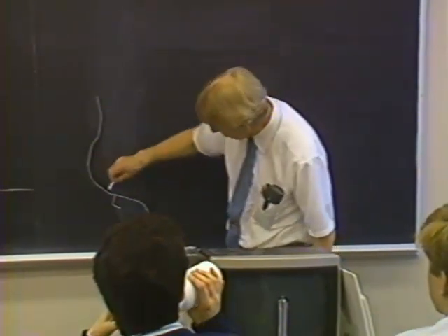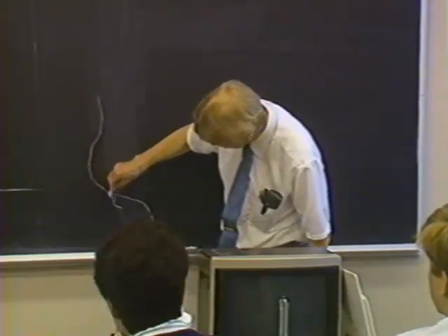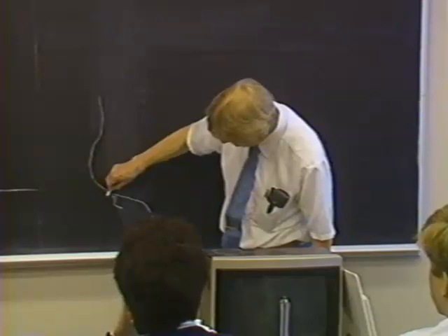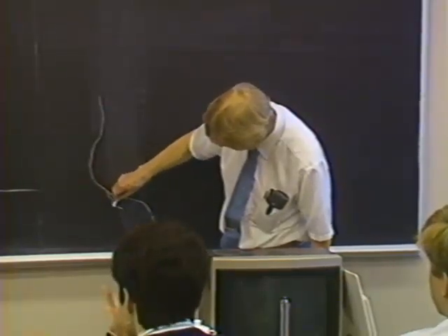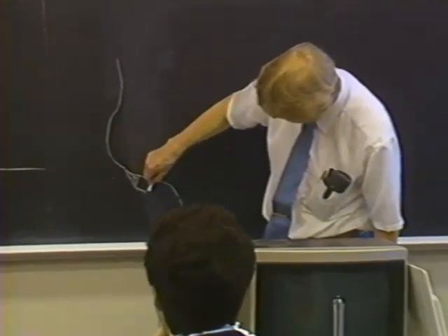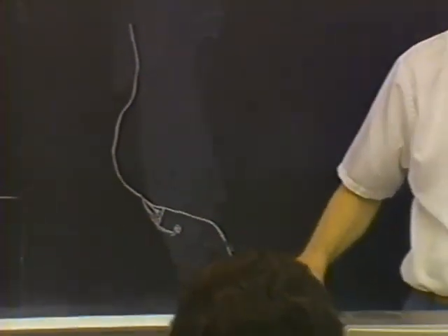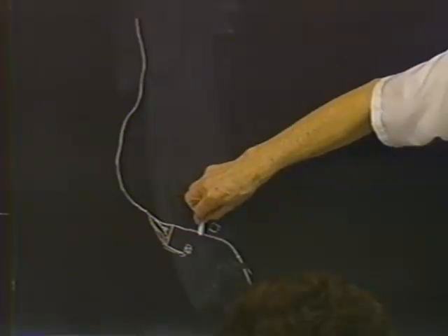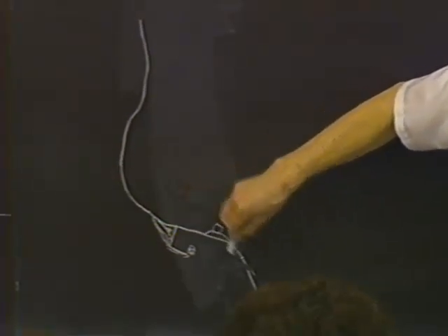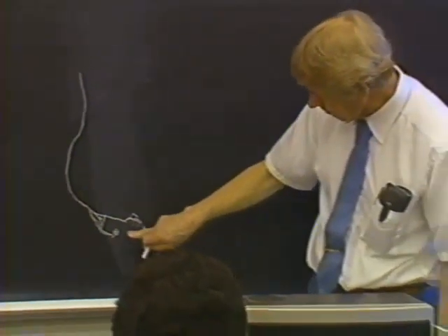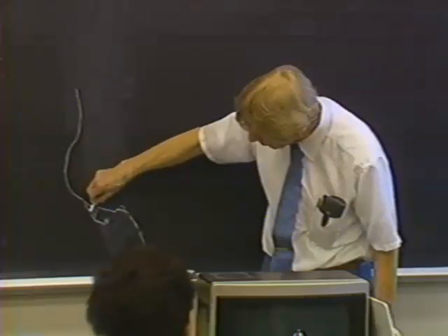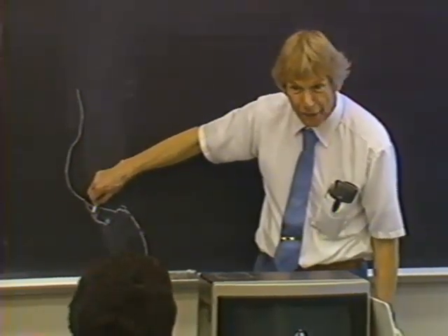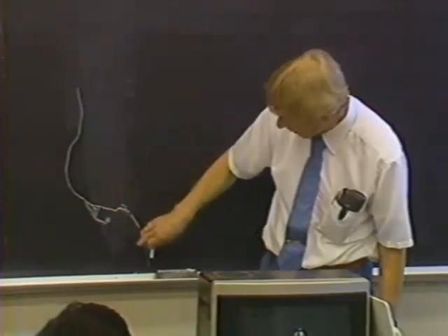And they found that in a short time, sand accumulated in a kind of fillet here, and then more sand accumulated, and finally accumulated clear out to the end, and it was transported along the end and then accumulated in here and blocked the entrance to their harbor. Not only that, but there were some resort hotels over here, and the sand beach that they used to have began to disappear. And pretty soon the water was right up at the front door of the hotel. And in fact now there's a high school here and a track and football field and so on, all out on the sand.